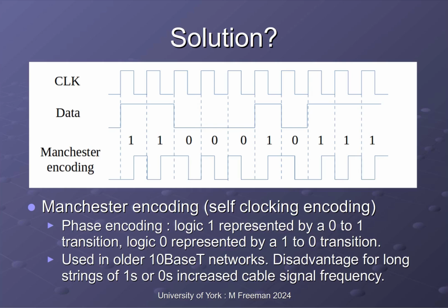So that's very nice from a clock regeneration point of view, but from a frequency component point of view, as you increase the frequency to achieve higher data rates, we start to see significantly higher frequencies. And as we discussed previously, there's a limit on how fast you can send data down that wire. There's a limit to what the maximum frequency is for a particular cable. So we want an encoding scheme that allows us to resynchronize our clock on the receiving end, but we want that encoding scheme not to increase the clock frequency too much. So you've got competing demands on your encoding scheme.